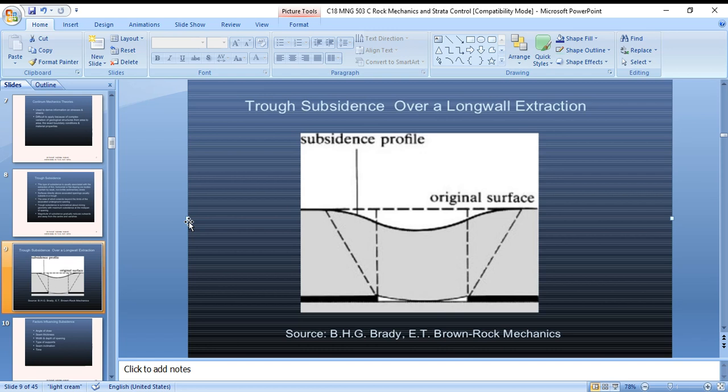Features of subsidence based on analysis of the vertical and lateral surface surveys have been summarized by the figure, with the acknowledged representation of the lateral displacement. Note that all the lateral surface displacements are towards the point over the center of the excavation, and they are zero at this point. The vertical surface displacement is maximum over the center of the excavation, and these displacements extend well beyond the lateral limit of the excavation.